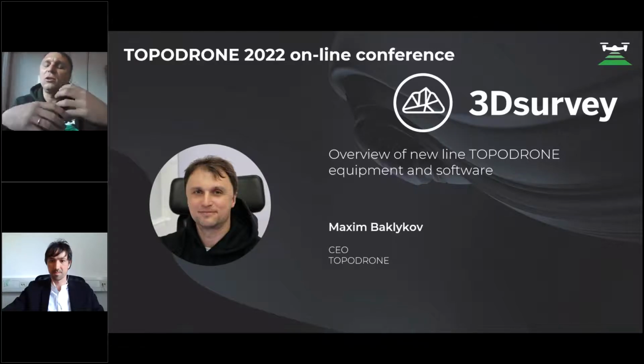You will easily get terrain level from LiDAR technology, and you can easily vectorize data using photogrammetry if you are going to vectorize roads or buildings and so on. And of course, photogrammetry helps to colorize the LiDAR point cloud, and the combination of both technologies provides the best results, which I saw before.